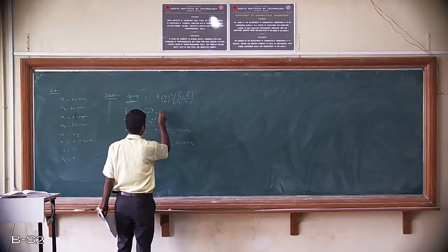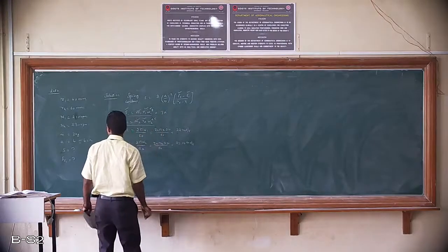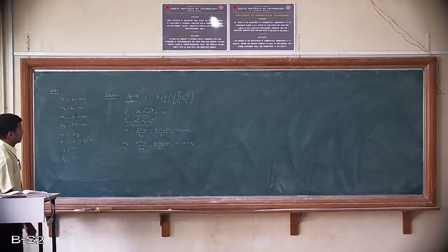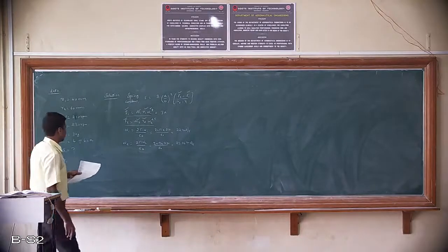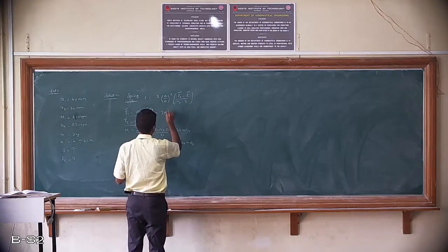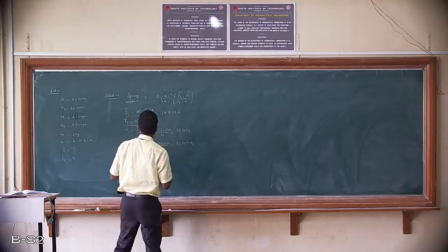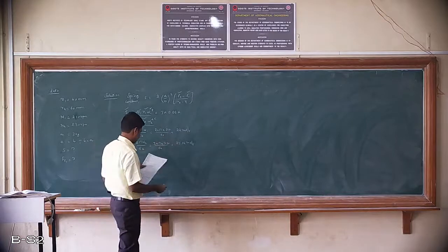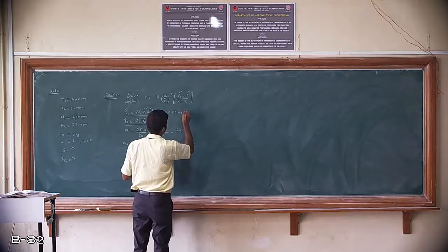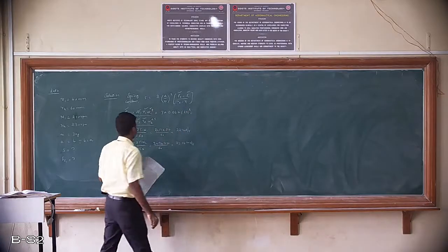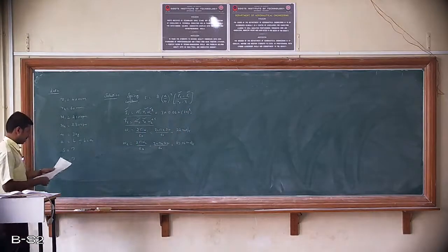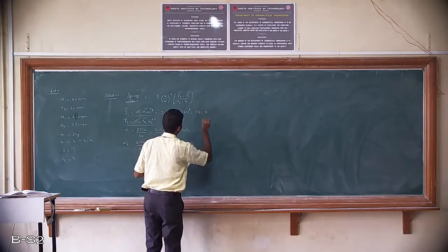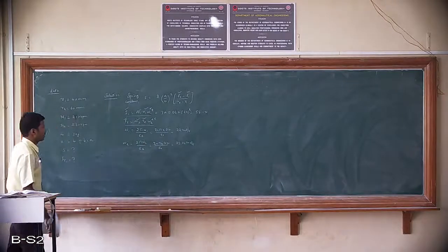So substitute the values of m1, r1 and omega 1. The value of m is 3 kg. The value of r1 is given in terms of mm, and I need to substitute it in terms of meters. So r1 is 40 mm, so it becomes 0.04, and next one is the value of omega 1. The value of omega 1 we have already calculated, that is 22, so it is 22 square. So we can get the value of F1, and the value of F1 is 58.1 Newton.